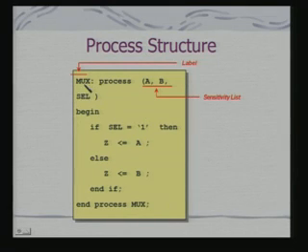The process is part of the architecture, okay, and A and B are the sensitivity list, these are the signals. If you remember, this is the same as before. What I am doing is basically designing a multiplexer. So, if select is 1, then output Z is A, else Z is equal to B. Okay. So, I am defining this behavior through this process structure.